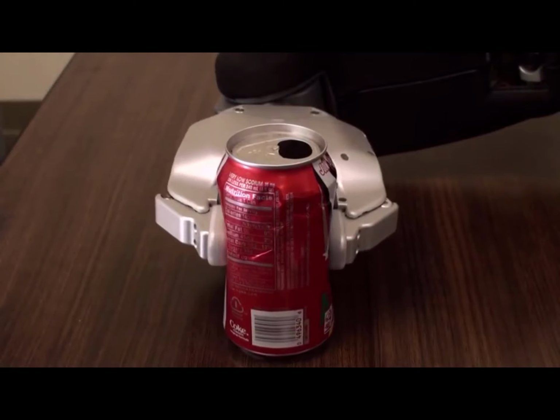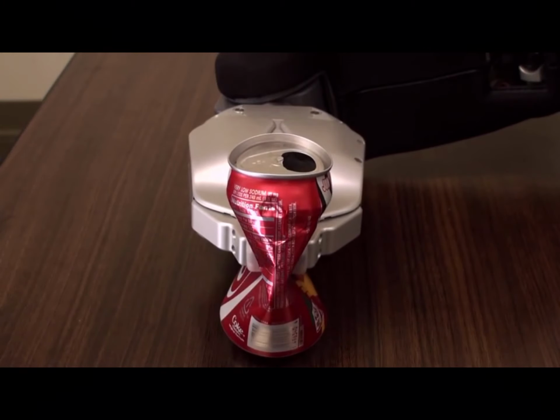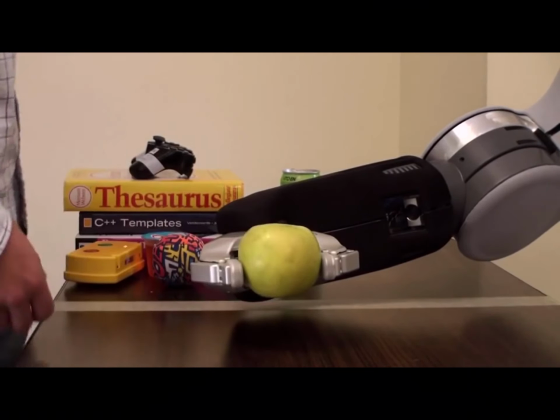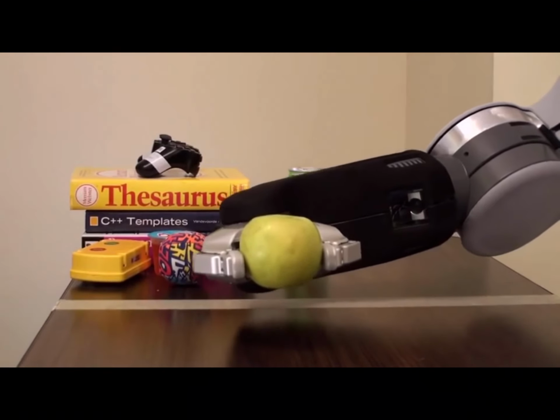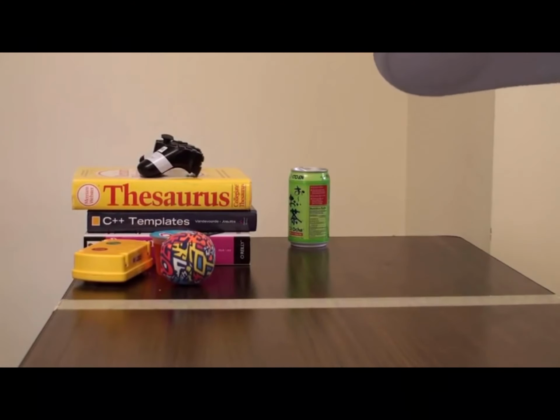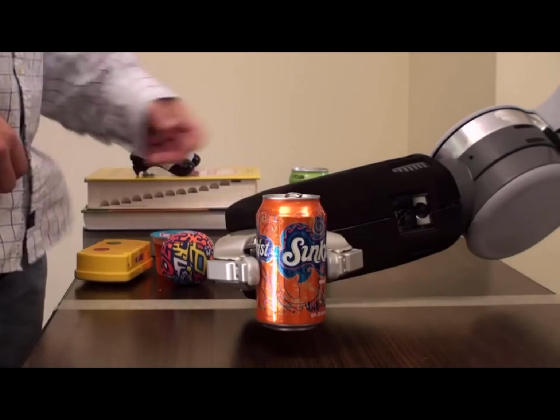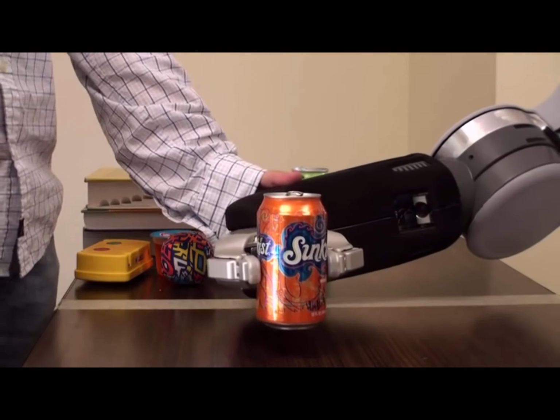Previously, without tactile feedback, the strong robot joints would crush many household objects and be unaware of unexpected contact events. Using sensors in the hand of the robot, we're able to do delicate and responsive control of the PR2 gripper. The robot is able to close its hand around objects in the world, recognize the moment of contact, and stop quickly before damaging the object.